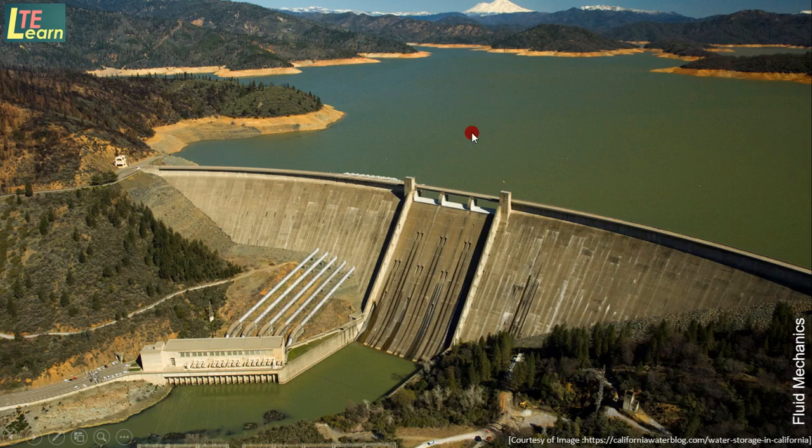So this acts equally in magnitude in all directions, as per Pascal's law. But vertically, this pressure varies as the height from the free liquid surface increases. That is what we are going to see.